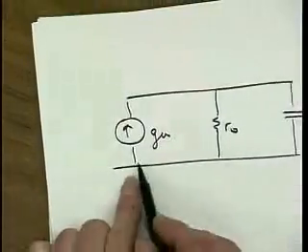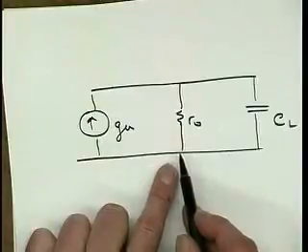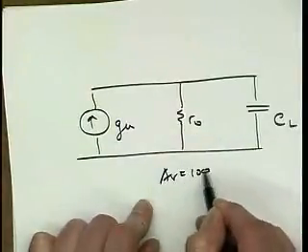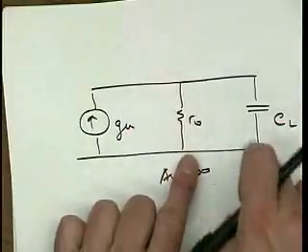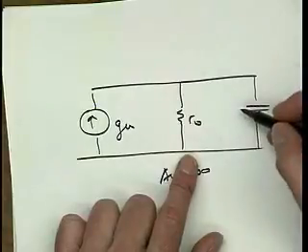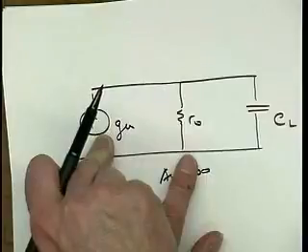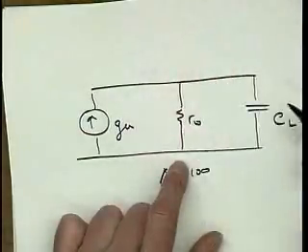at low frequency, all the current runs into ro, and we get a gain of, let's say, 100 or so, right? But at high frequency, ultimately that gain goes to 0. Well, why is it? Well, because the transconductor still delivers the same current, but the impedance here decreased by a factor of 100.